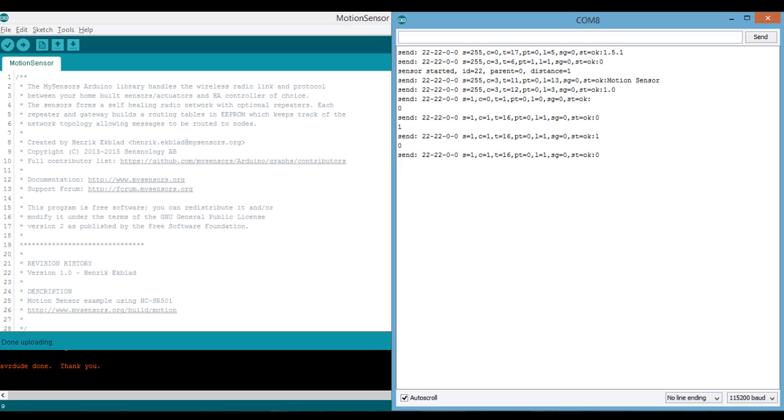If something's not working correctly, occasionally you'll see it in here. Sometimes you'll see a status fail or a miswired message, and then you could check your wiring for that. If you see status fail, that's probably a hardware issue. So you can bring the gateway closer to test that, and then I'll go into some other troubleshooting steps on the hardware side in a second here.